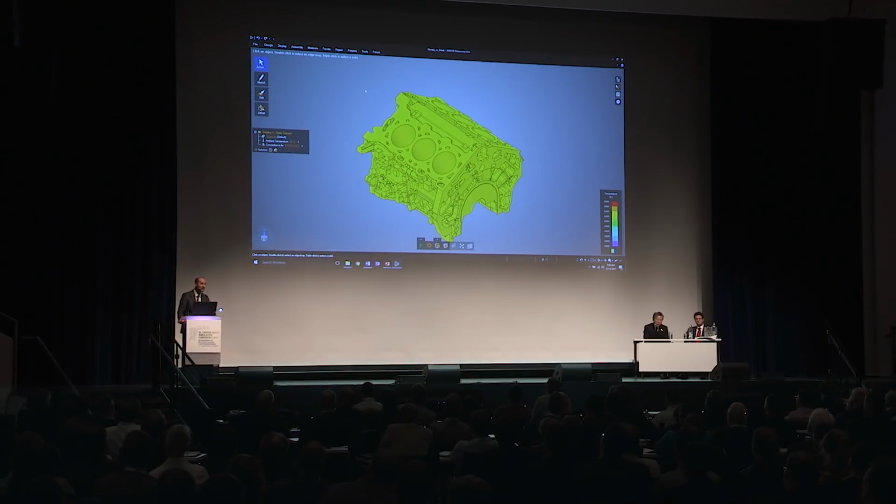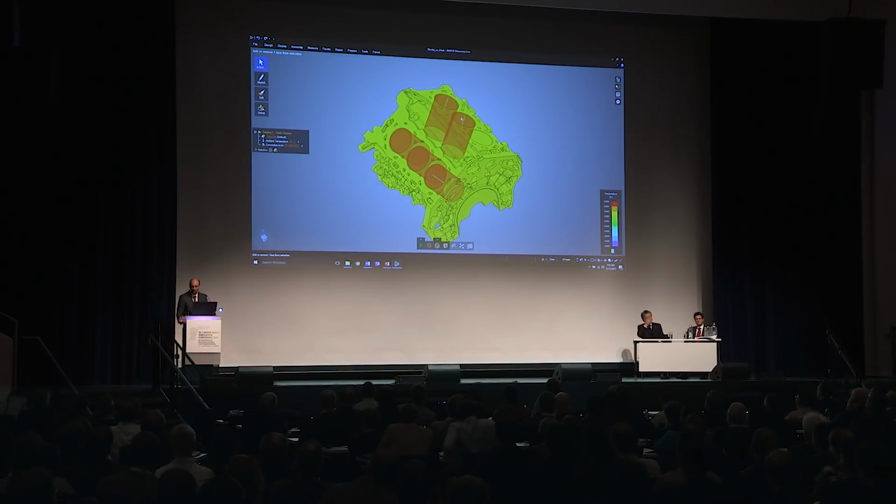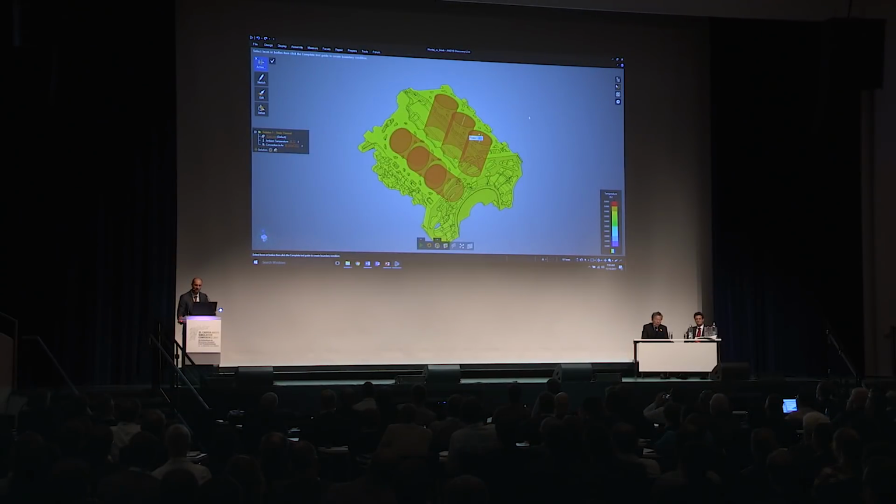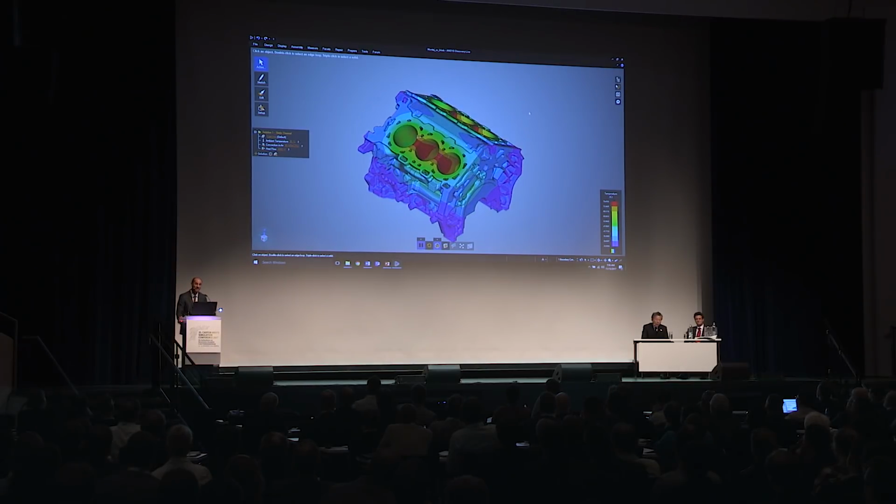Aha! All right. By default, this is thrown into convection. You can change any of these defaults that we pick. But we'll assign, just like I mentioned, one boundary condition to illustrate. And we'll pick all of these cylinders because we can. And we'll assign that heat flow. Let's say, in this case, it's going to be a lot. Maybe 2,000 watts, 2 kilowatts of power that's going to be assigned here. This is the other copy we opened. It took me longer to open the file, longer to type in the number, but the results are still instantaneous.